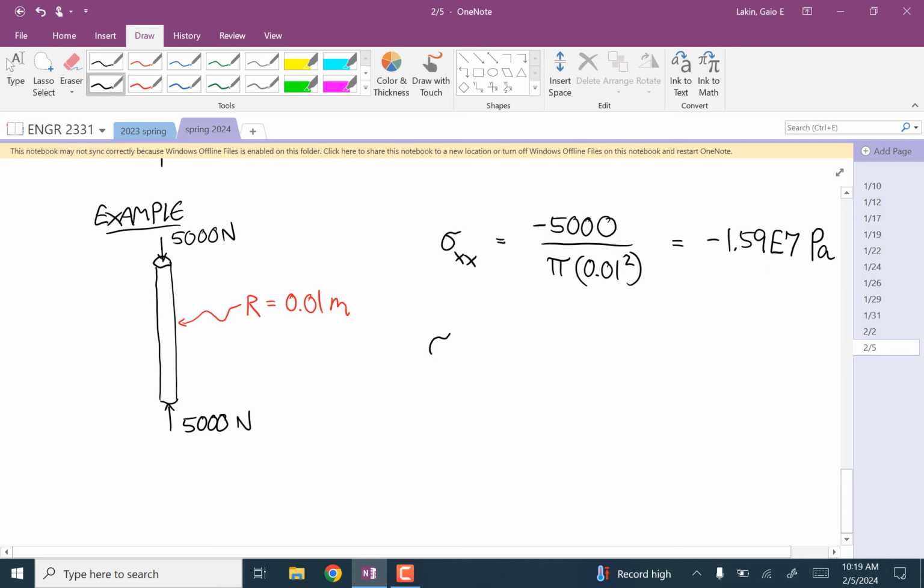And so the stress tensor, and remember that stresses are valid for a single point, right? So let me just try to speak carefully about this. What we're calculating is the stress at every point in that member as long as you're away from those two loading points, those two ends. Yes? Because we're assuming it's a distributed load across the entire surface, it doesn't matter if we're off the center axis. That's right. Yep. We could be way out at the edge.